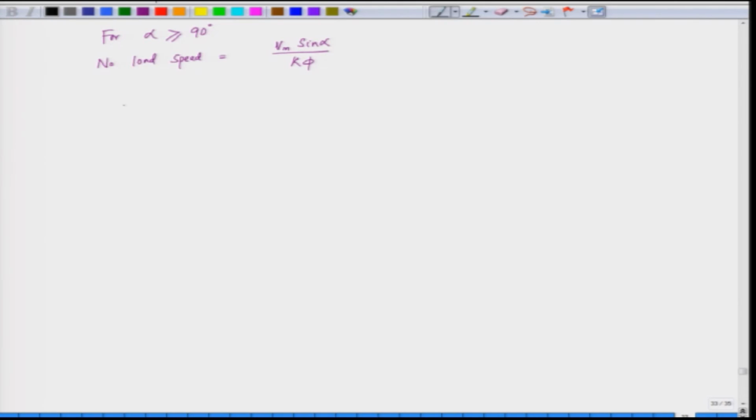So, now in this case we have the motoring. So, the motoring is a straightforward case. So, for motoring we have this half control bridge where we have thyristor and diode, and this is the armature circuit.